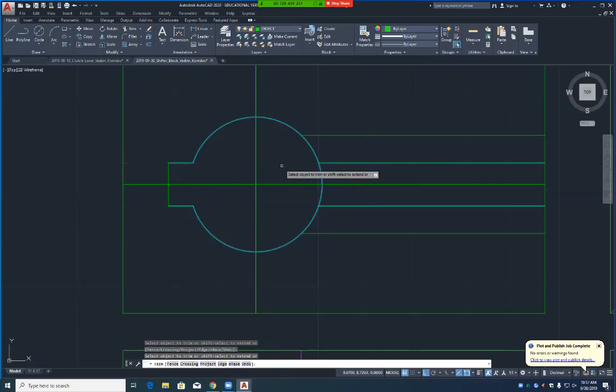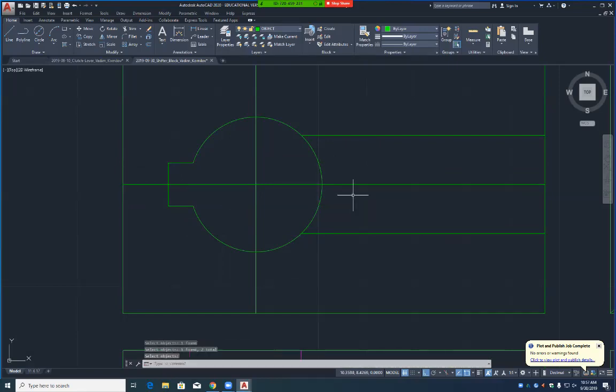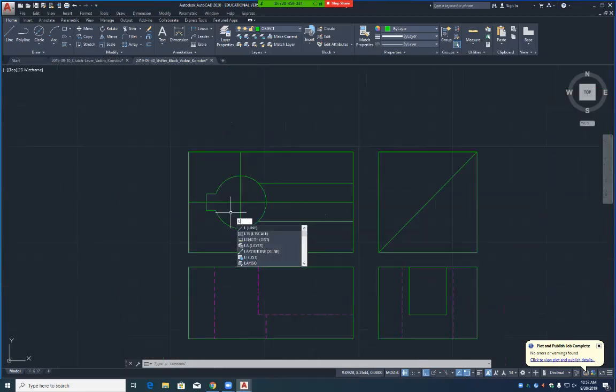Okay, now, super critical concept. Is this line here correct right now? No. It isn't, is it? Why? Because of the keyway. I no longer have anything right here at the quadrant point, do I? I cut it out, haven't I? But you have those sharp angles. Right. And so what I've got to do is pull this point here down to here. That is my new hidden line, or this line here moves over to here, doesn't it?